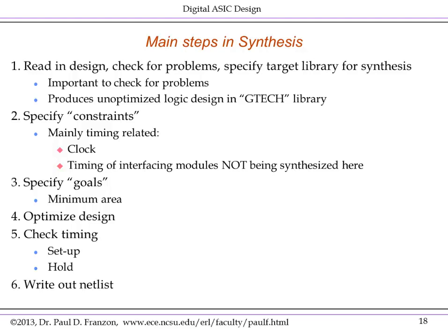You then optimize the design. This is the actual logic optimization step. And remember, this is the core of the algorithms here, because what they do is they try to produce the minimum logic while also meeting the timing constraints. We then check the timing, set up and hold, get the tool to fix any hold violations if they occur, and write out the netlist. So let's look at the read and the constraints aspects.